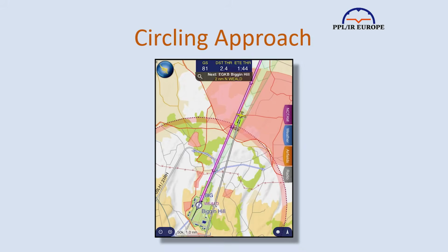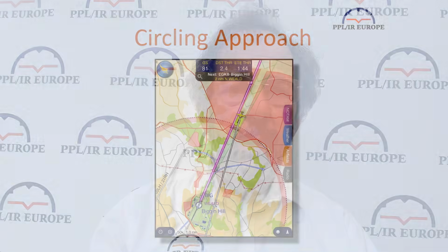And I also have SkyDemon running, as it provides yet more orientation assistance, though it's yet another thing to look at and can mean your eyes are pulled away from the runway and the panel, so it depends again on workload. So, in summary, circling approaches carry risk and challenges. Circling approaches have high workload entailing quick decision making, precise control and situational awareness. They carry a risk of spatial disorientation, especially if visibility varies or fluctuates.